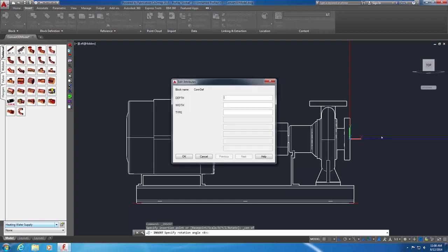If the dialog does not appear and AutoCAD prompts in the command line, set ATTDIA and ATTREQ to 1, and repeat the steps. For depth and width, enter the number 5. Enter round for the type. The depth and width for piping must be the same value as piping is round. Entering different values results in an oval shape. The type can be set to round, as is appropriate for pipes and round ducts, or to rectangular for ducts. Click OK to save these attributes to the inserted block.